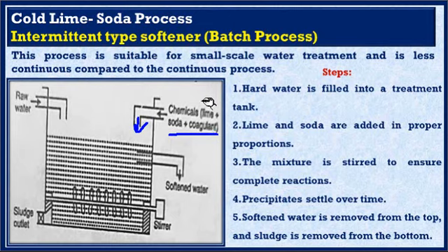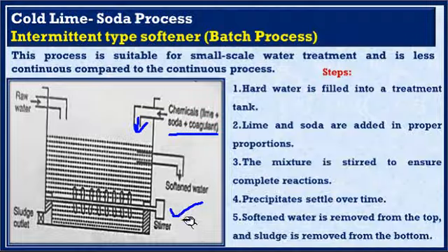And raw water is passed from one side, and the mixture of lime and soda is passed simultaneously from the opposite side, and stirring is started with the help of this stirrer. A small amount of precipitate from previous treatment is also added during the stirring. Why? Because these small amounts of precipitate particles act as a nucleus for the new PPT.